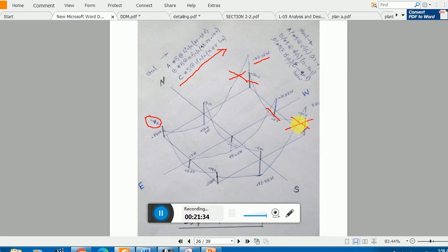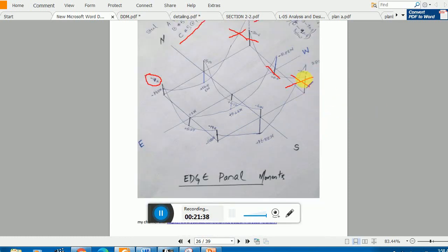This means in the longitudinal direction movement is maximum, so that is negative movement. This means that you have to place bar in top portion. Here you have to place bar in top portion, okay, to gain the maximum. Let me show you the bar placing.